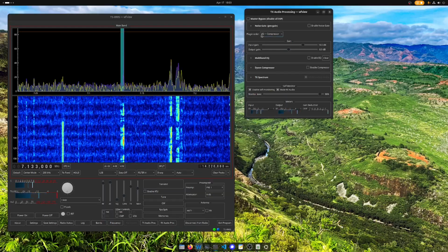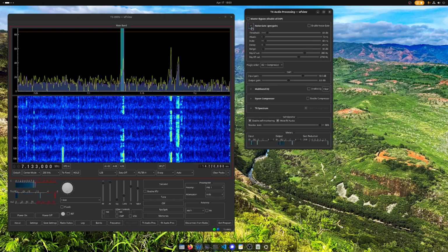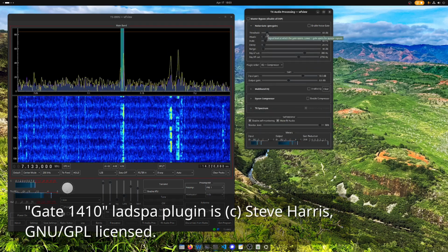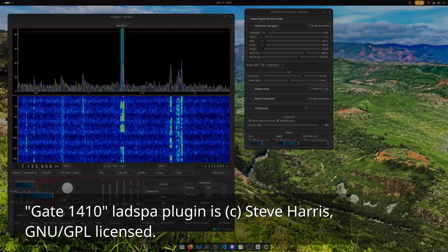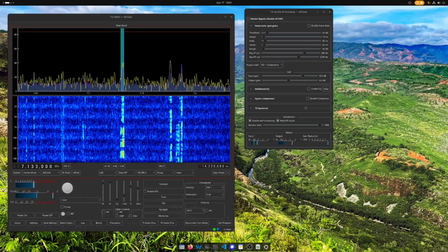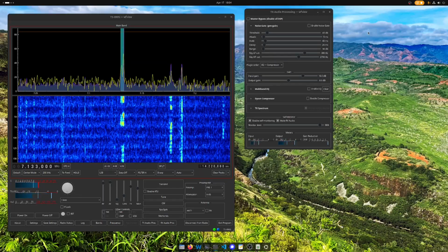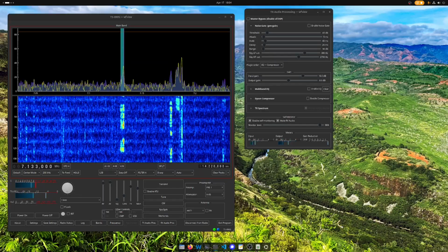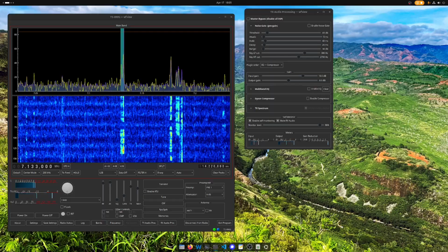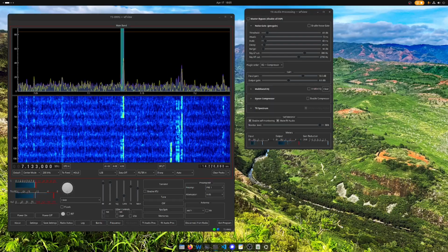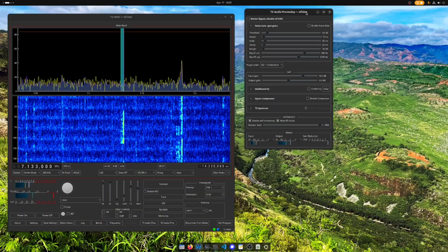And so the first thing I'm going to do is set the noise gate up. And to make this even more interesting, I'm going to turn on an air filter in the room. So I'm going to start by turning on noise gate to remove the sound of the background. And that can be significant sometimes, especially if you're running an amplifier and you have a lot of power coming out in between words. You don't want all this power coming out, right? So plus you don't want to sound like a leaf blower.